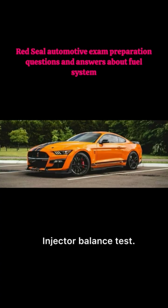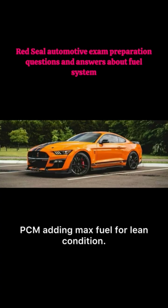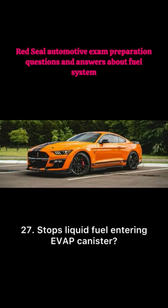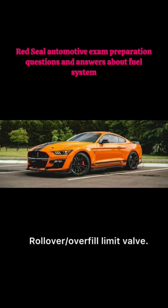24. Test for sticking injector. Injector balance test. 25. Fuel trim plus 25% means PCM adding max fuel for lean condition. 26. Charcoal canister purpose. Stores fuel vapors from tank. 27. Stops liquid fuel entering EVAP canister. Rollover overfill limit valve.